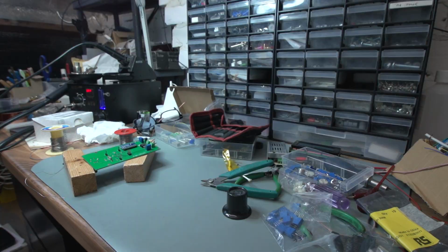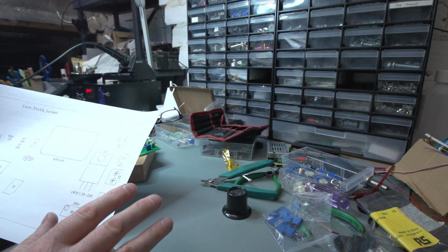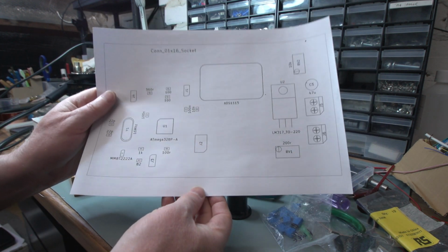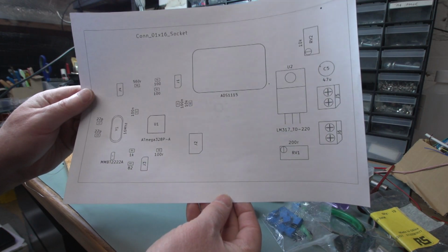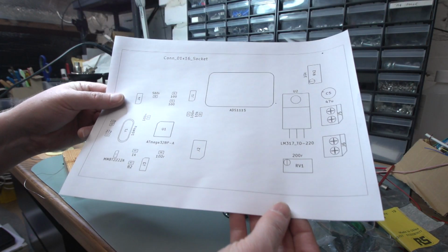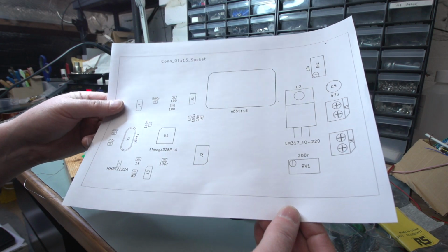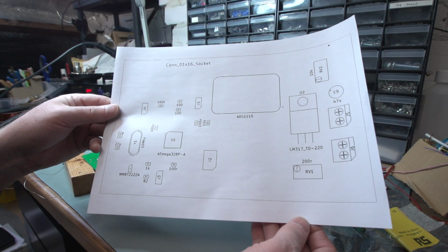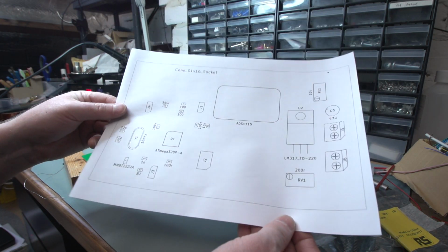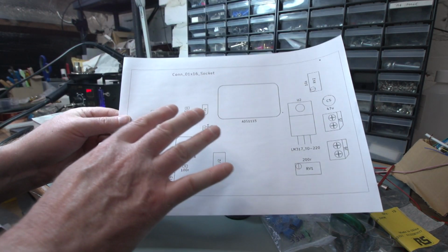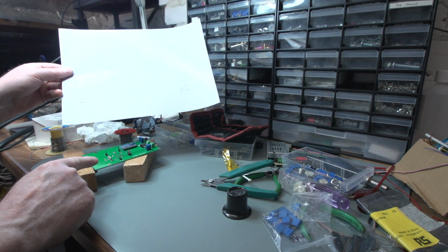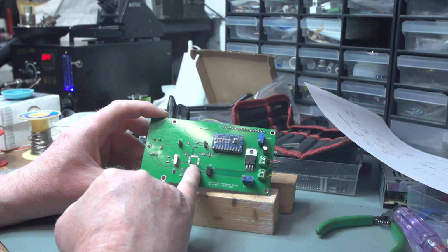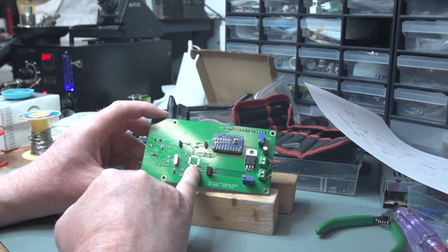Now, one thing I forgot to mention was, of course, it's always a good idea to print out the fabrication layer from the PCB design. Indeed, that's exactly what the fabrication layer is for. So if you print out the fabrication layer straight from one of your Gerber file exports using the Gerber viewer in KiCad, you can use this as a template, a guide rather, for when you come to populate the board. Alright, so that's the board populated except for the MCU, the 328P, and that should arrive tomorrow.